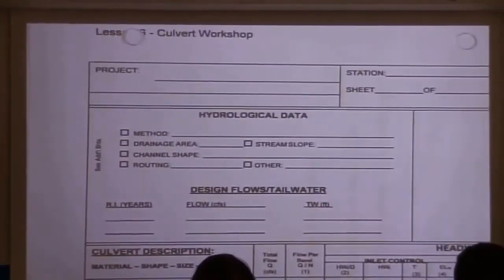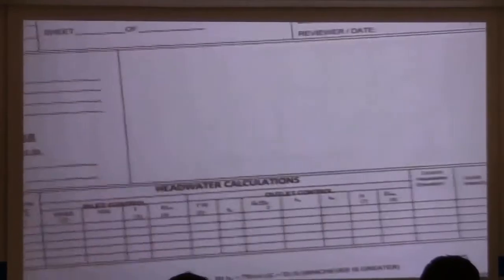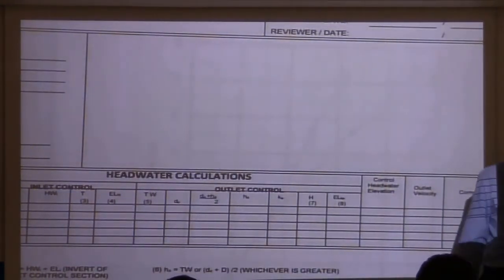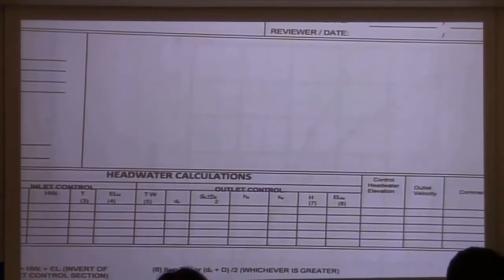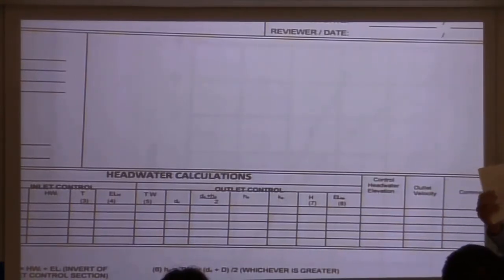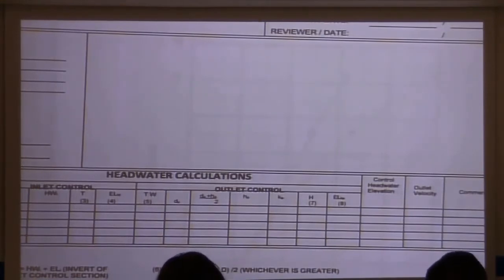So the first part is a little bit tedious. We have to plug in, you should have this sheet here. It looks like this worksheet. And we now have to plug in all of our given information in here. There should actually be a culvert diagram right here. So your worksheet, the one that you can get out of HDS5, should have a culvert diagram here, and then you can just label all of the different elevations in it. This will be a little bit tedious, but you do have that on the given information on page 2. So it's just a matter of translating the figure on page 2 into here. Not a big deal.